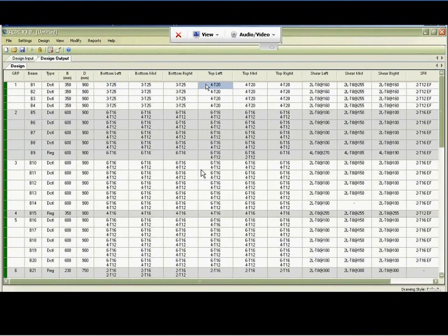The moment I do that, the software will detail with the information that we provided. So here you can see all the bottom gets detailed with 25, top gets detailed with 20 as required. So that's why we didn't specify a number. It's evolved a number as per the requirement of the detailing in itself. So you can control detailing across a section or across an entire beam group using these tools.